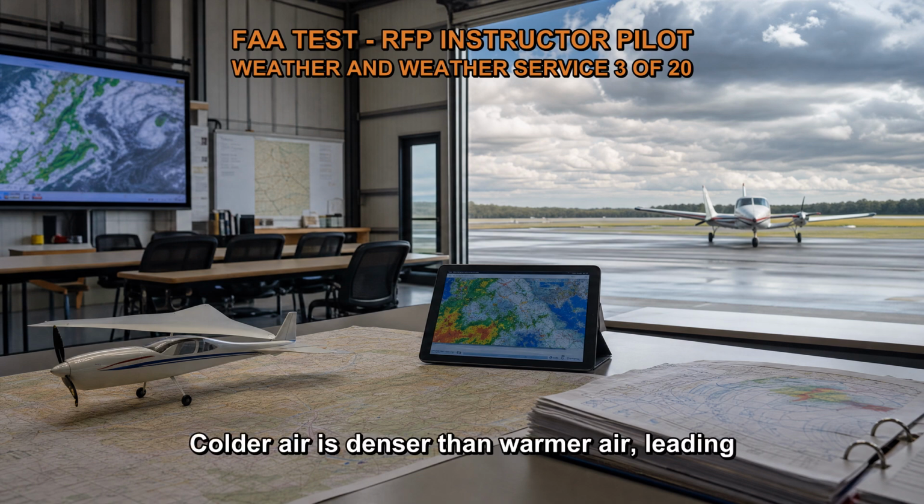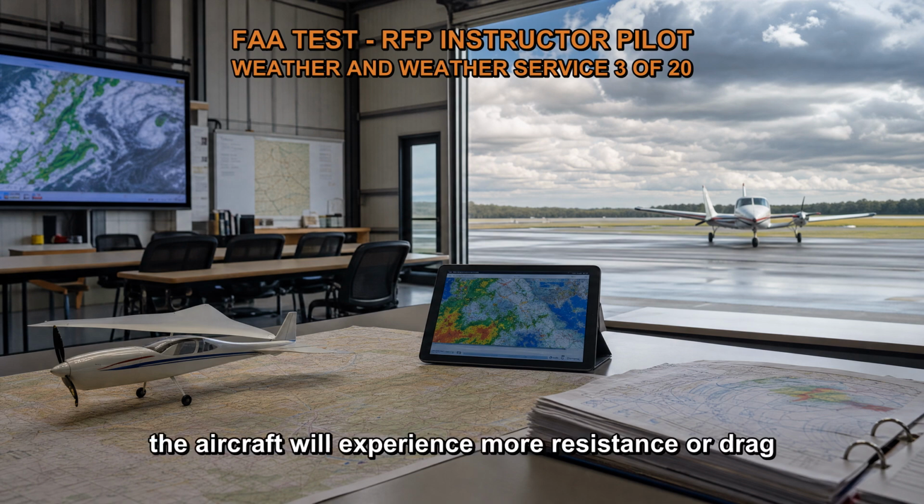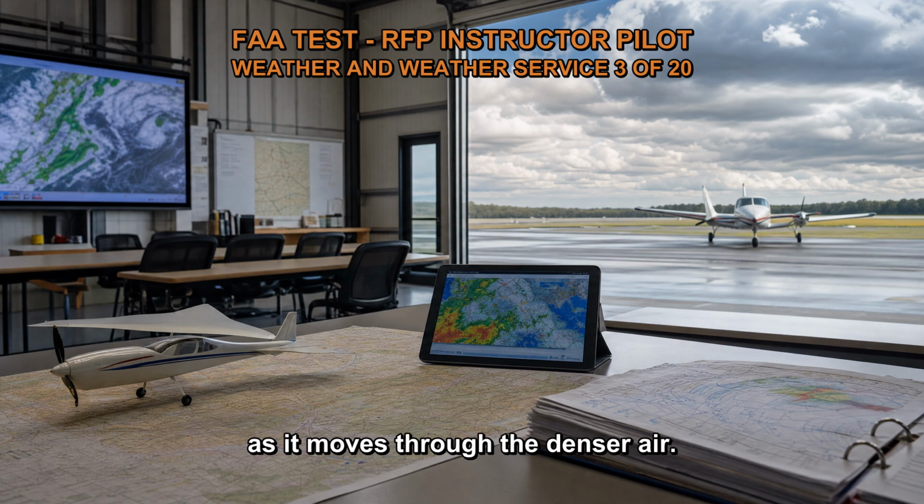Colder air is denser than warmer air, leading to an increase in air density. An increase in air density affects an aircraft's performance in several ways. As the OAT decreases and air density increases, the aircraft will experience more resistance or drag as it moves through the denser air. This increased drag results in a decrease in true airspeed for a given power setting. In other words, the aircraft will fly slower through the denser air.